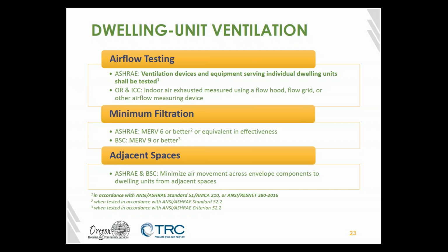And then within this, once you've installed, there's also a whole world of confirming and commissioning and testing that these were installed properly. First, of course, is airflow testing. You can put on a flow hood, or a few other different airflow testing methodologies, and test that those devices are actually providing the 45 CFM that you calculated is needed for that particular apartment. You also confirm that the filtration system is installed, has the right MERV value on it, and is accessible.